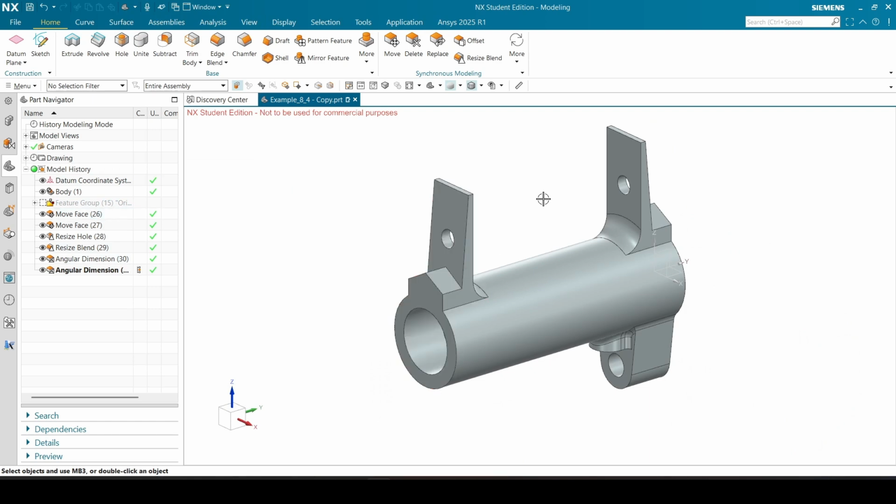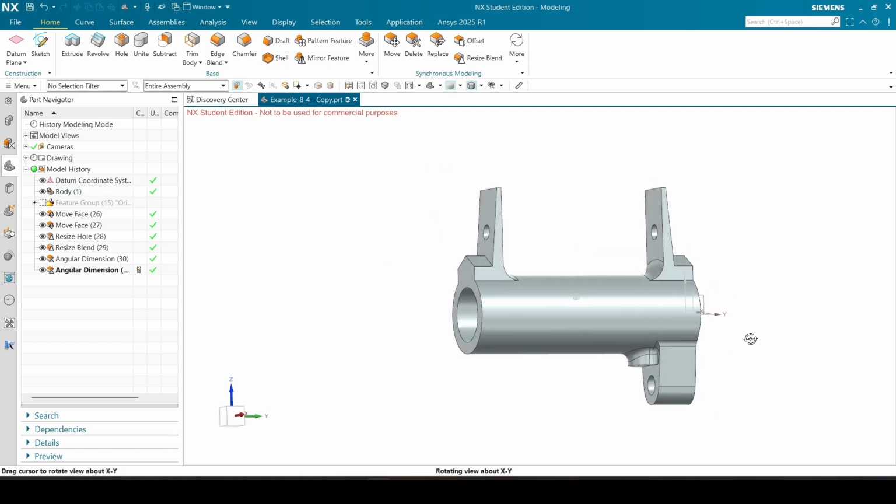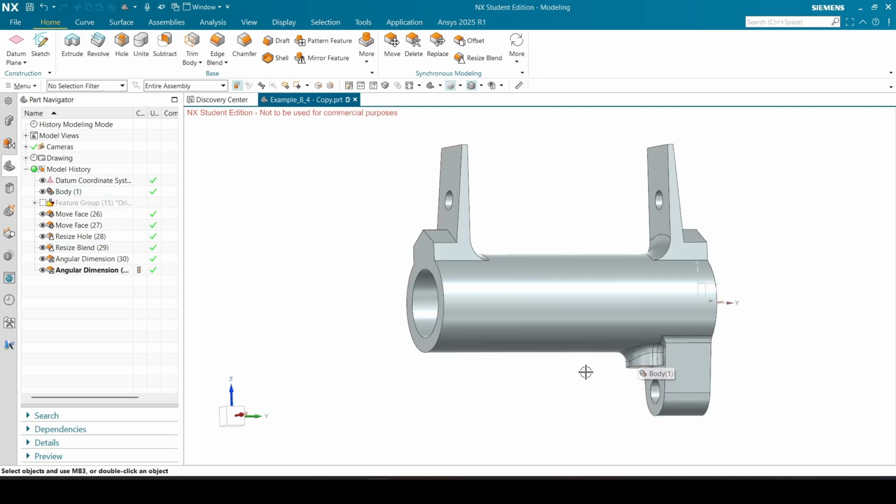Okay, so now we have all those top things. Now we move down to the bottom. First I'm going to jump to the left sketch, or let me quickly show you. If you don't move to the left sketch, you see here's an angle to put in for this face. The problem is you have edge blends, and if you change that angle, you're going to start interfering with that edge blend and it won't work.